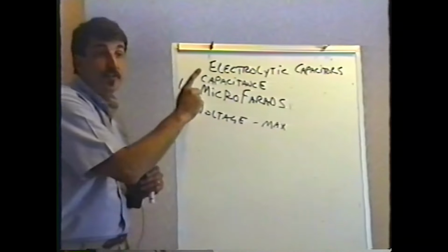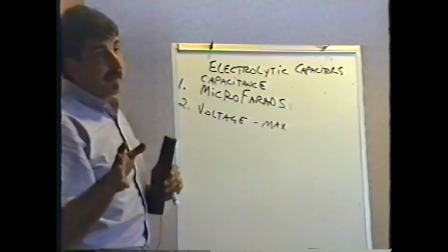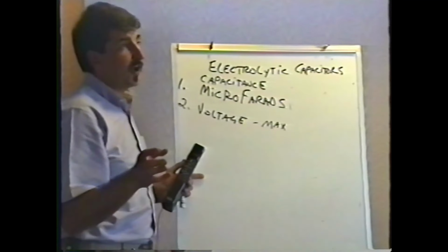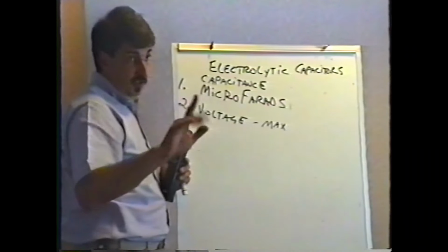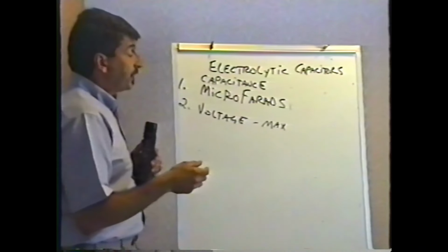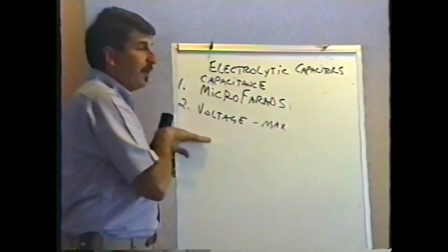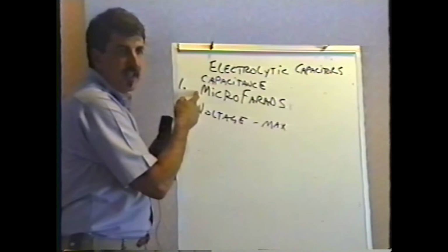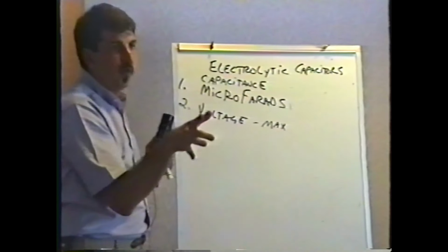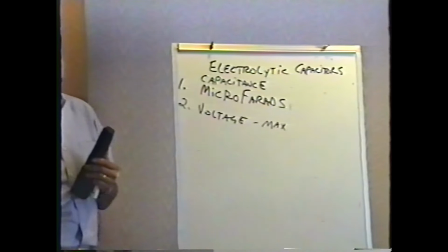In many cases, you can go up in microfarads as well, but you have to be careful about that. And at this point, you folks are not advanced enough to know what I'm talking about in terms of when you can do it. I'll show you later on, though. Primarily, for now, let's leave it at this. You can always use a capacitor with the same or higher voltage, but the number of microfarads should be the same when you change capacitors. For now, I will tell you places where you can actually get away with more capacitance, and it works perfectly okay.